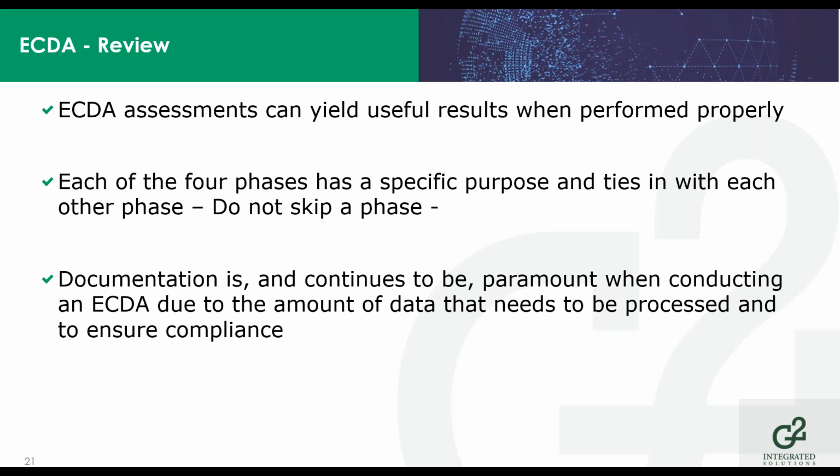So to wrap up here, ECDA assessments, they can really give you some useful results if you do it right. They can give you some great data, a great picture of what your pipeline looks like from an external corrosion point of view. Again, each of the 4 phases has a specific purpose and will tie in with the other phases. Don't skip them. And then documentation.